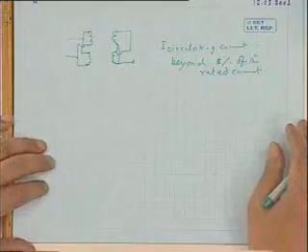Therefore, to summarize what we have discussed so far: if you want to parallel single phase transformers, the most essential condition is that the polarities must be correct. That is the first thing. Then impedances should be inversely proportional to their KVAs. As far as possible, you try to meet that. And thirdly, even if the voltage ratios are slightly different, this should not cause a circulating current, even under open circuit condition, which will exceed about 5 to 10% of the rated current. I have written just 8% like that. So these are the three things.